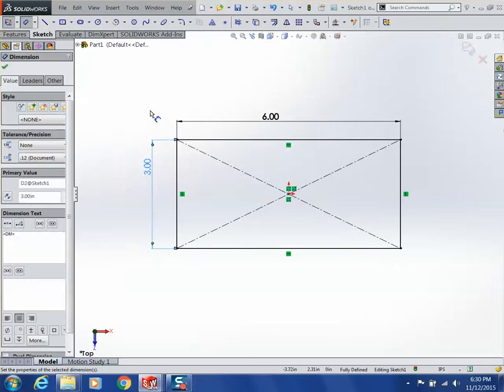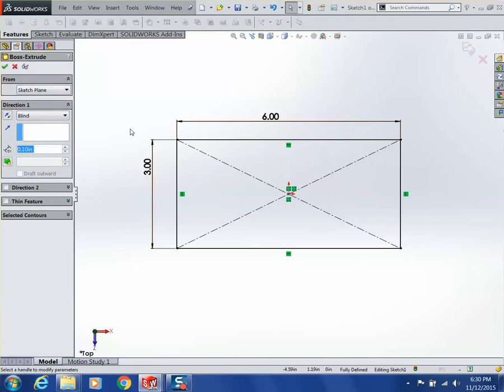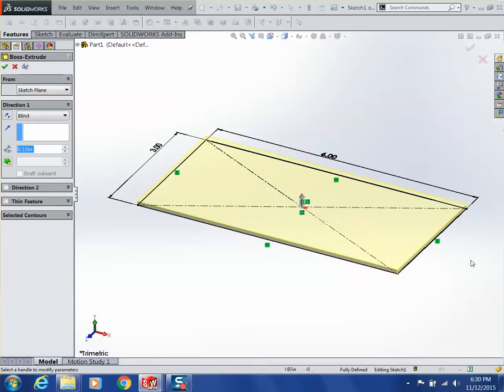Right. If you go this way, now what you're left with is planes that run through the center of the part, and by the time we go through here and make this into a plate, you've got edges of the plate way out on the edges that you can use for reference on stuff. And you've got planes that run through the middle that you can now use to reference things. That comes in really beneficial when you start mating things together.